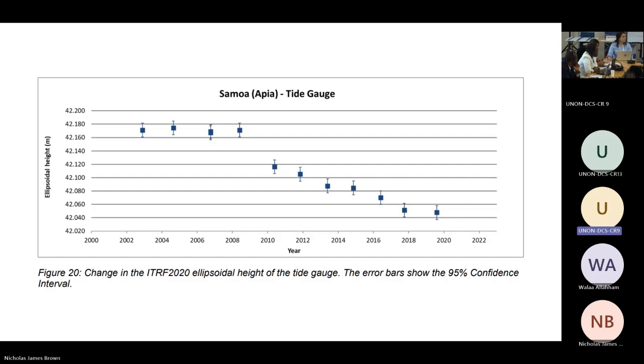So they're using tide predictions, and the tide predictions are developed based on the tidal data they got from that tide gauge. Ideally, you would have about 20 years' worth of data to create good tide predictions based on that Earth-Moon relationship. So they're using GPS to get their latitude and longitude, and then their height is the sea level based on the tide predictions with respect to the bathymetry.